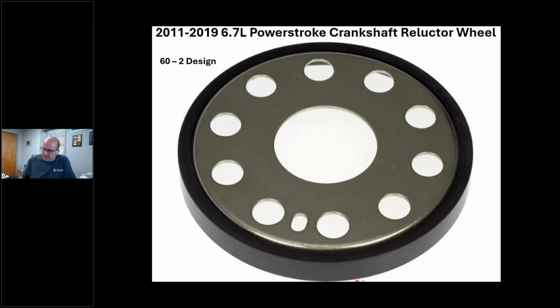Now, I can't see the teeth in this magnetic encoder ring, but believe me, there's room for 60 teeth, and there's only 58 of them. So, hey, we've seen these things fail in the Eco Diesel, have we not? A Chrysler, we've changed quite a few of these. They come in, they don't start. I'm sure if you guys have worked on some cars, you've seen this issue.